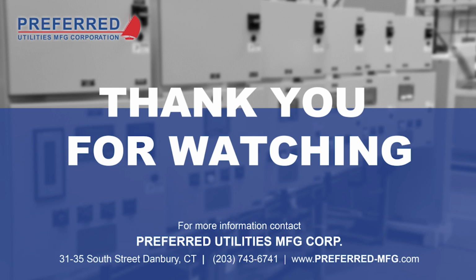And quite honestly, grounding on any of these systems anymore, because they're microprocessor based, checking grounds is one of the first things I think anyone should do, regardless if there's issues. They used to make those 10,000 volt ignition transformers, and those grounded to themselves, right? But nowadays, all you ever see are the 5,000 volt or 6,000 volt ones, and they all ground through the burner, right? Well, that's what I've seen for gas applications.